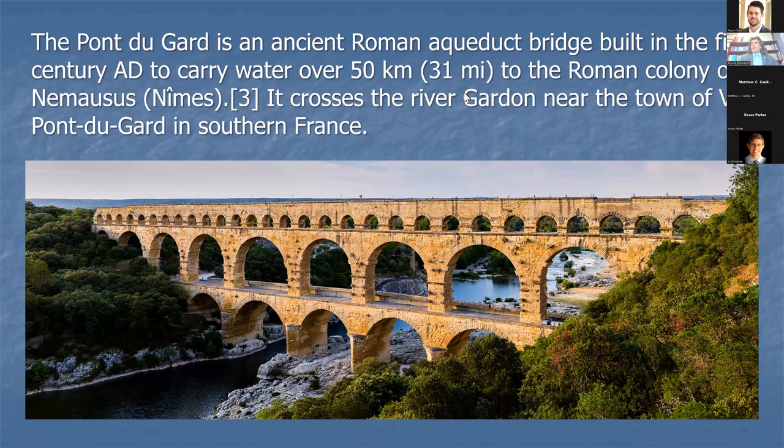Actually, I admire the innovation that went into bridge engineering at the time when there was no steel. The shape that you see down here, the arch, exists because at the time there was no material that would take tension. So they had to use an arch, because it resists compression. And that's why the structure is so massive. In fact, you see that in old buildings, for example in many churches in Europe, the Middle East, and so on, the same type of structure, because there was no material that would take tension.